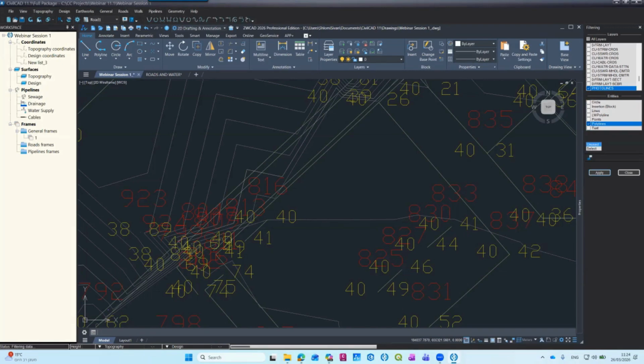Okay, so you can see below the system what it does now. It scans the entire drawing with the entire 3D polylines, convert them into break lines, which will apply to the topography surface. The nice thing now is that in the past, it used to ask you a lot of questions, whether you want to add points, not. Now, everything is automatic. It means if on the vertex of the break line there is a point, it will not be created in the list. If it does not have, automatically it will be appended to the list below.